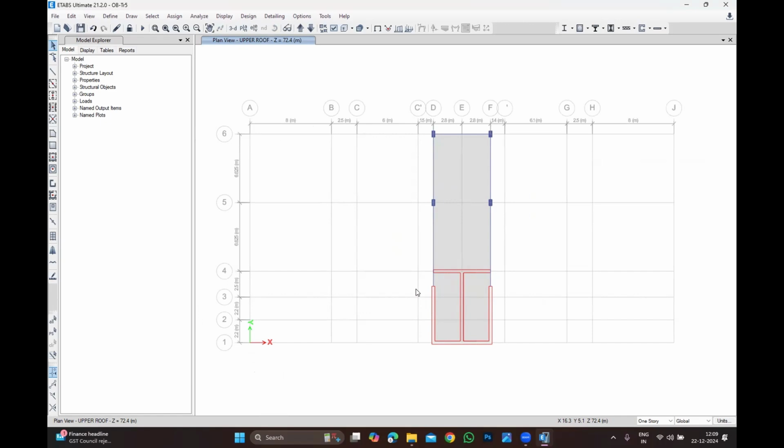Two different colors actually. Now it is gray color, right? There it moves like a little darker gray. So definitely warnings will be created. In the analysis actually, you will not get a difference in the result, to be honest. Because it's a minor gravity load difference, no? 240 mm slab thickness multiplied by 25. It's a minor gravity load. It will not show much difference in gravity load. But what will be the problem? Warnings will come. Even so, it doesn't matter actually. That's not a big deal.